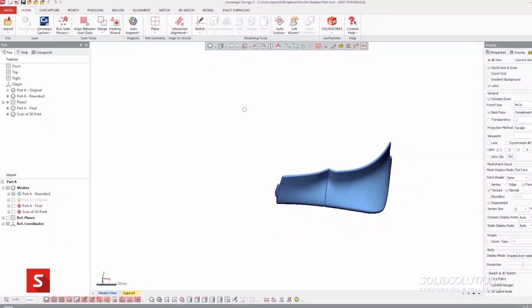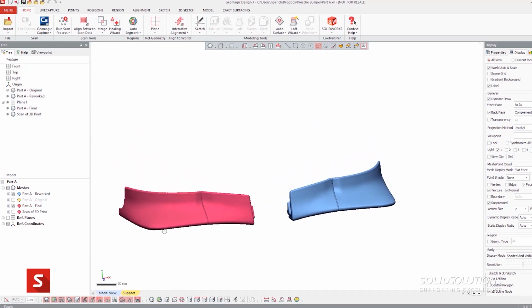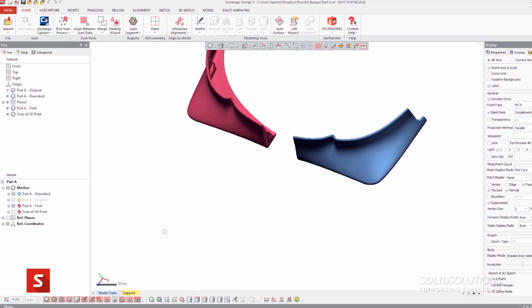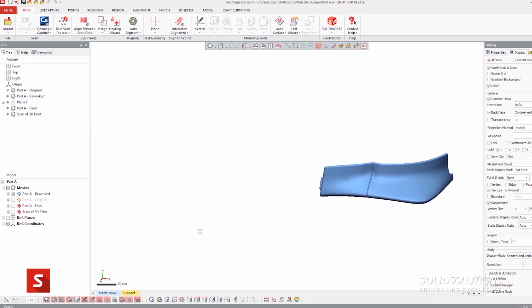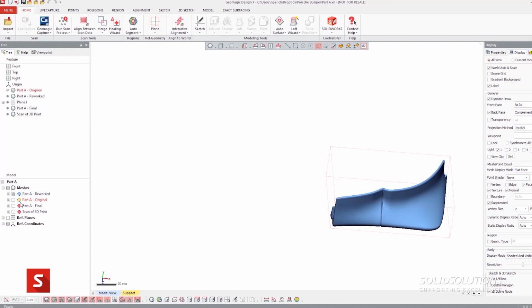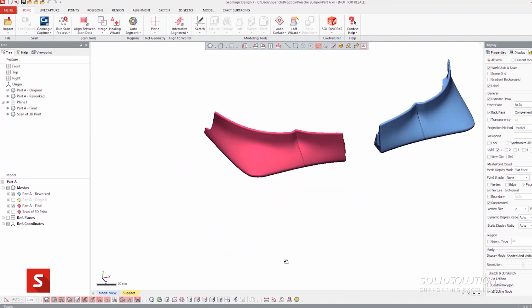So he sent us the side that he did have, and we 3D scanned it, flipped it round to the opposite direction, and I tidied up the mesh a little bit after scanning it, and then we printed it pretty much as it was. So we're talking maybe an hour, maybe an hour and a half for the whole process. It comes together very quickly, but you haven't got that dimensional control like you would with a design intent model.